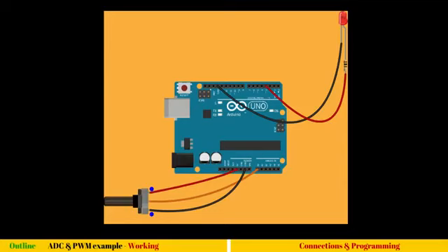So from end to end you get 5 volts, and when you turn the knob, at the center point, when you measure with respect to ground, you get 0, 1, 2, 3, 4, 5 and in between values also. So it's a continuous knob like the audio knob in your audio player. When you move to the extreme right, you will get the full 5 volts, and when you are at center you get 2.5, and when you are at extreme left you get 0. Right? So this way we are using this as an analog input. By rotating the knob we will get different voltages at different rotations.